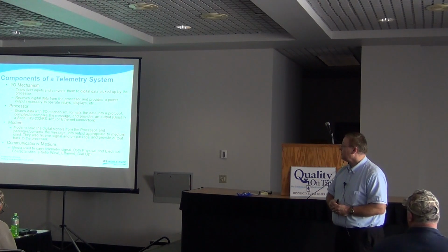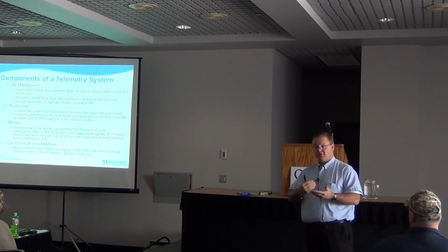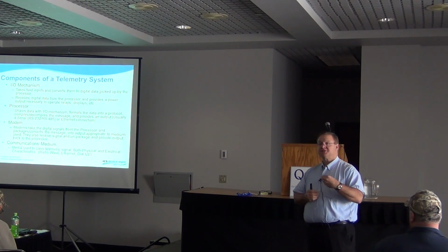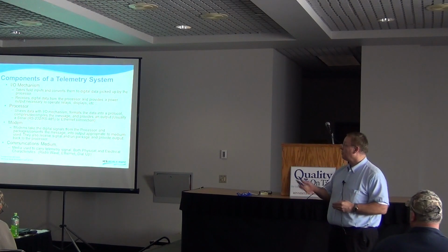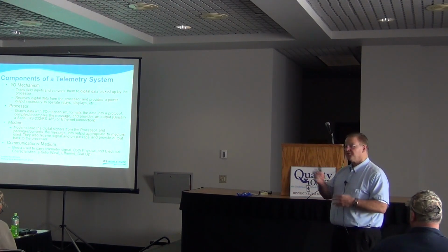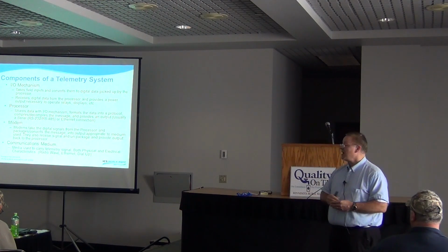Some components of telemetry. You've got an I/O mechanism. This is built into the controller. It converts that output from the sensor into a low-level electrical signal that's monitored by the processor. The processor is what takes that data, matches it up. It'll have a modem on it.